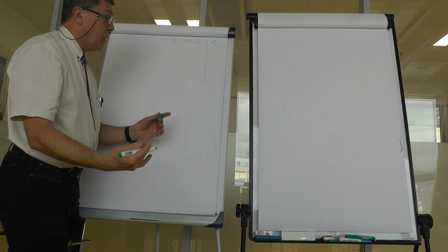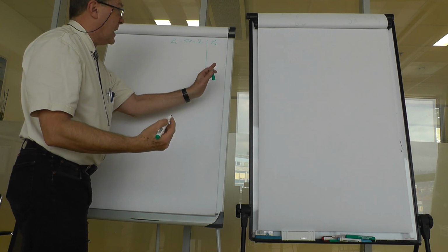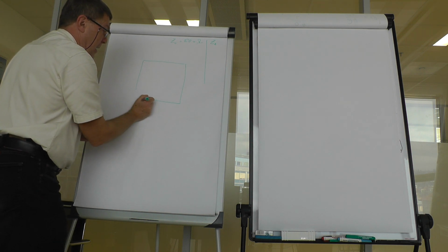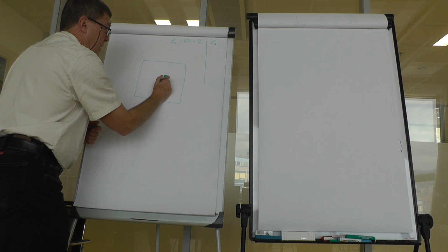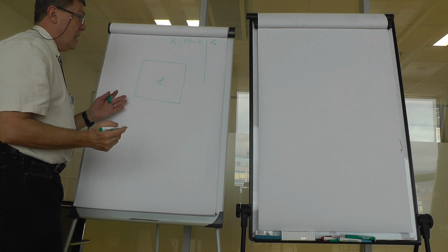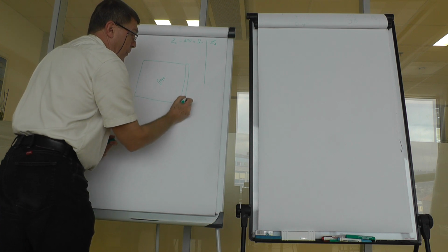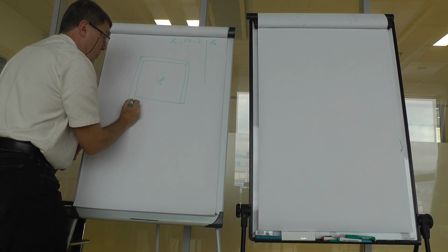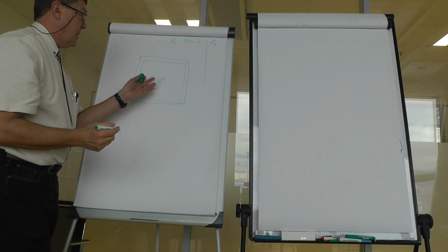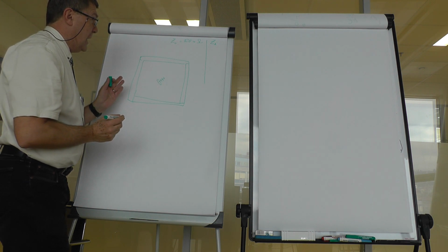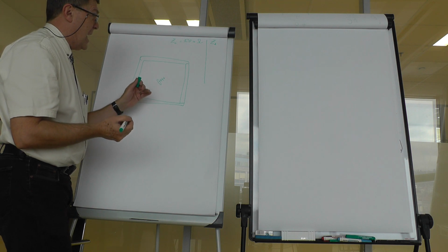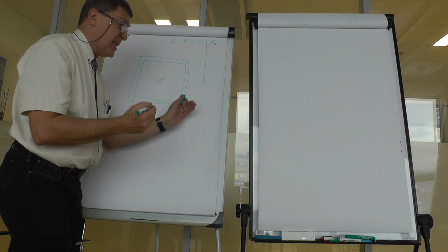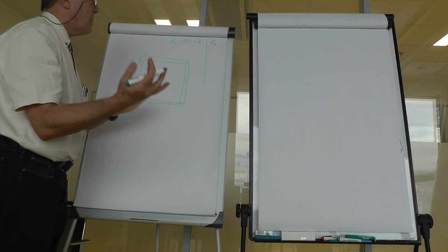And we have to have a finite grid. So for example, if you describe an antenna, you create something like a big grid. There is the antenna inside, and you would like to finish the grid somehow, to terminate it with some non-reflecting walls or boundaries or layers. So to do that, we would need to create some surface that is both absorbing and at the same time non-reflecting. Now what the problem in it is?